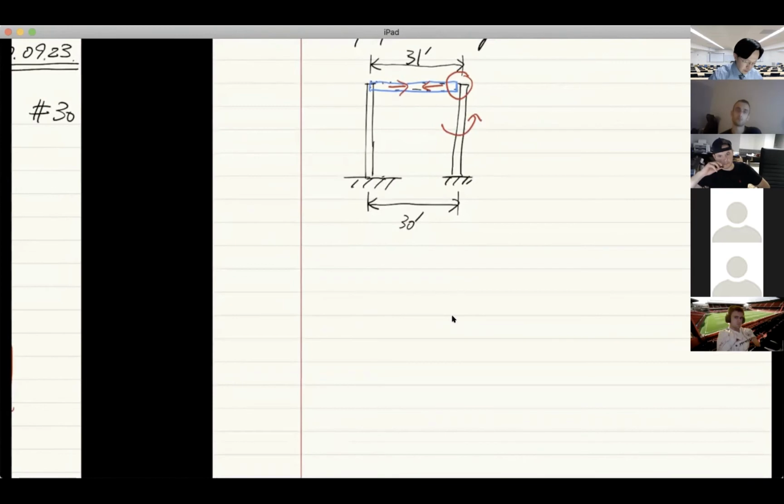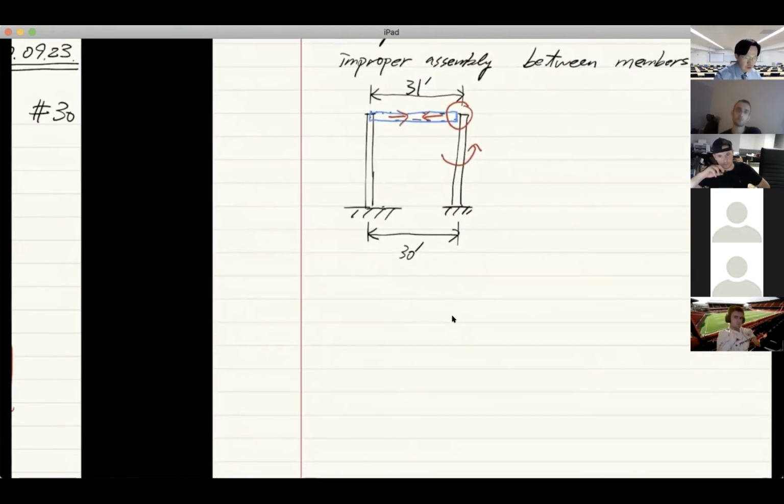Now, the third clarification today, which perhaps is an even more important one because some students asked me this question the first week, is about why the internal moment m sub int has the expression of negative EI times y double prime. I also had similar questions asked in the second week. Today, in 2 examples, we're going to use different expressions of internal moment.